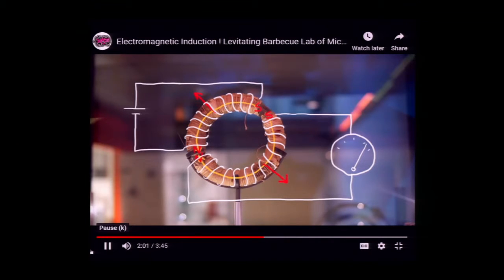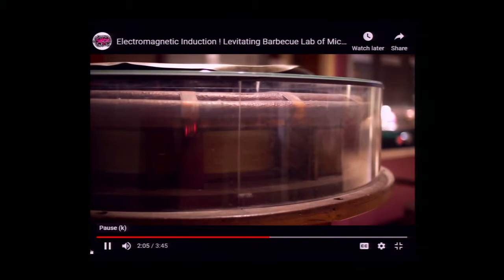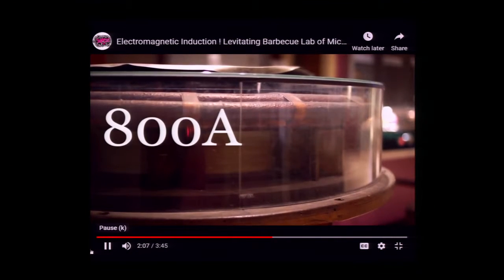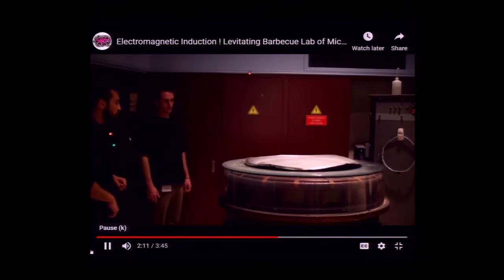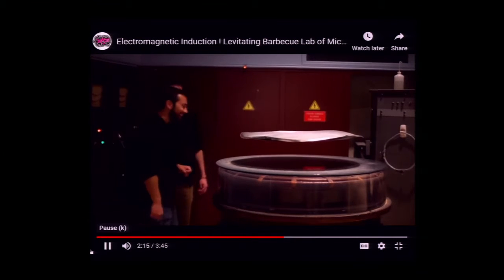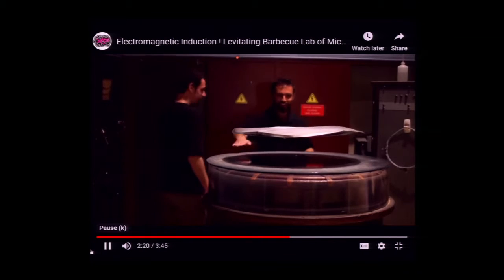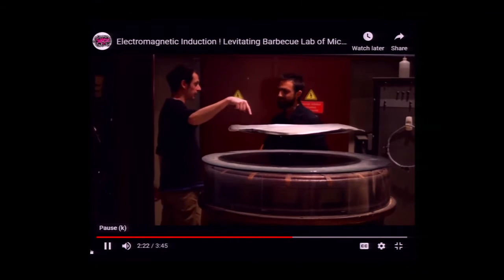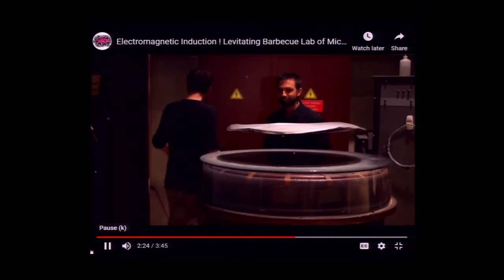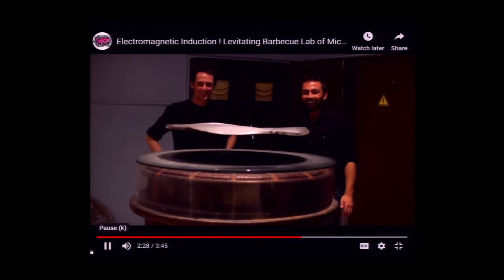Which brings us back to this. Through the bottom coil, we are passing a huge electric current, 800 amps, which alternates in direction 900 times per second. This ensures there will always be a changing magnetic field above the coil. Instead of the second coil, we're using the aluminum plate, but the principle is the same. The changing magnetic field induces currents in the plate that create an opposing magnetic field, so it levitates. How awesome is that?